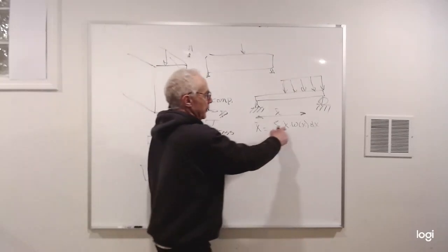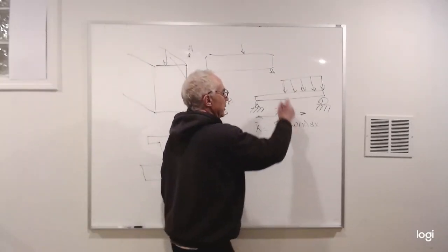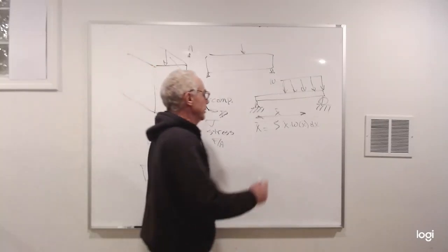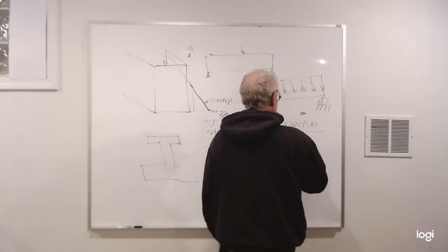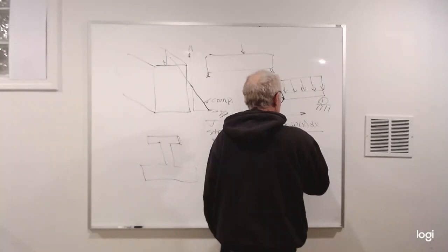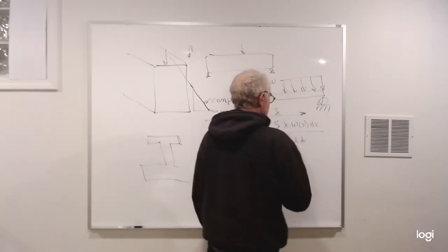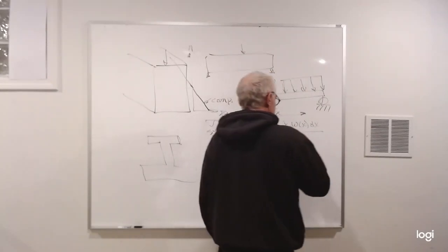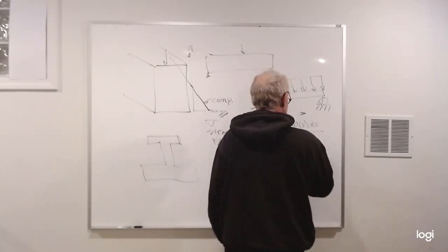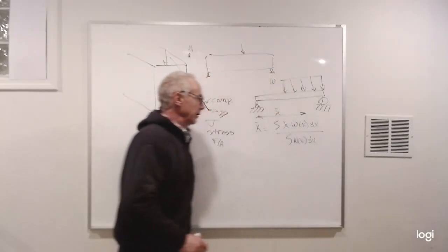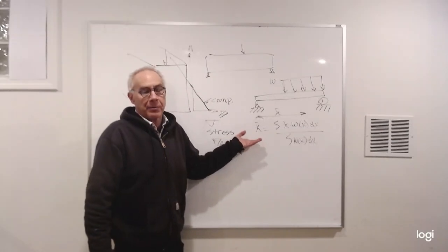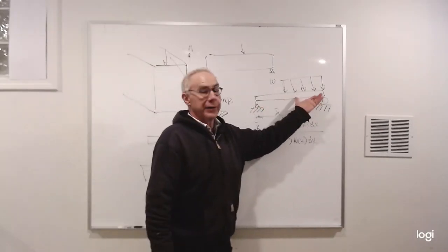That's essentially the first moment, where w is our distributed load, and that's divided by w dx. And this could be a w that varies over the length. Okay, so that's what we were talking about before. Oh, and this x bar is essentially a centroid of this area.